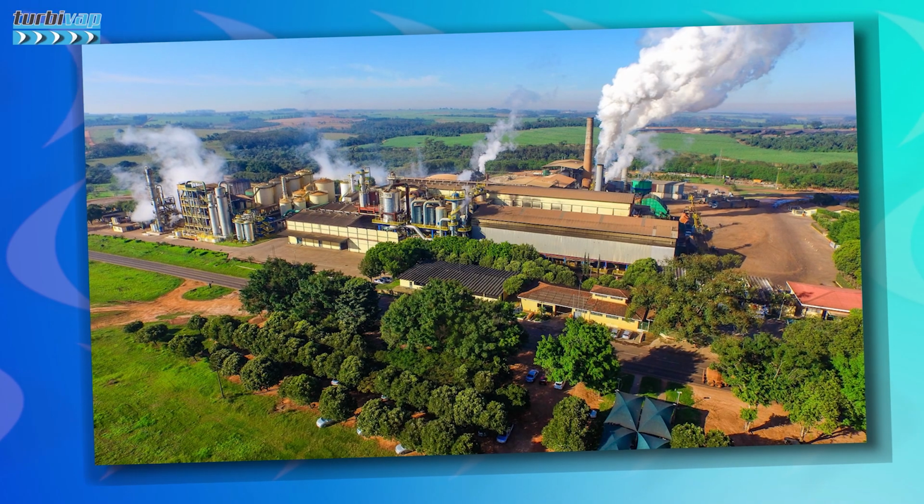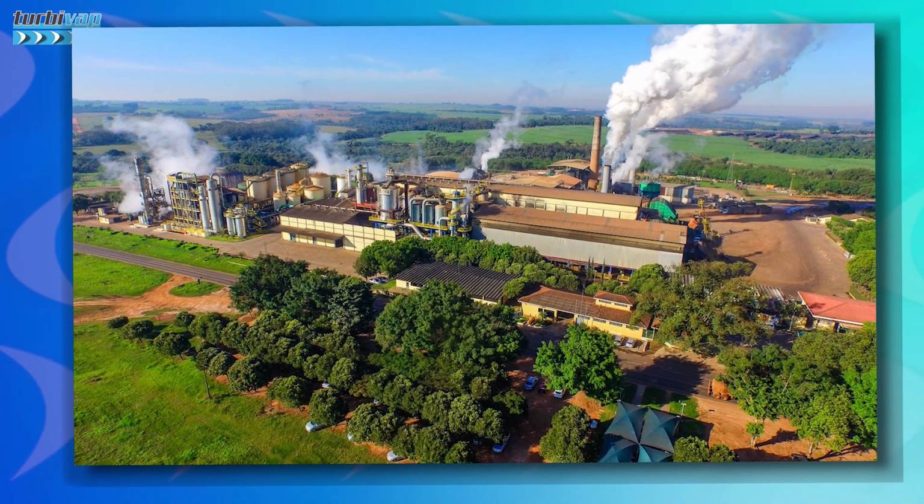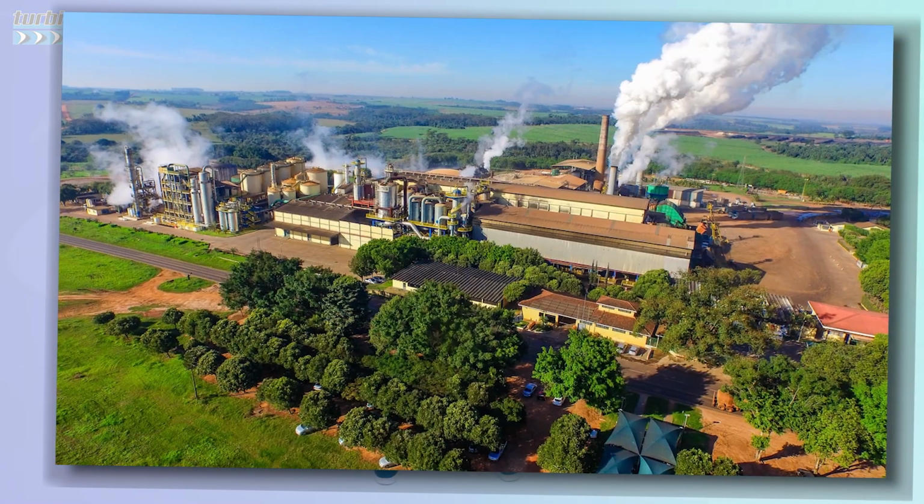In this case, the working fluid in the Rankine cycle is steam. It follows a closed circuit and is constantly reused. Water vapor, which is normally seen leaving thermal plants into the atmosphere, is actually generated by the cooling system and not by the closed steam circuit. This represents the loss of heat that cannot be converted into work.